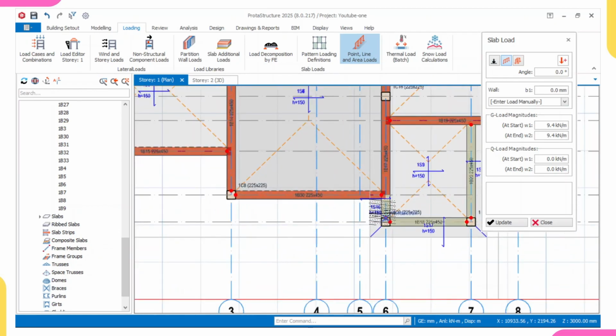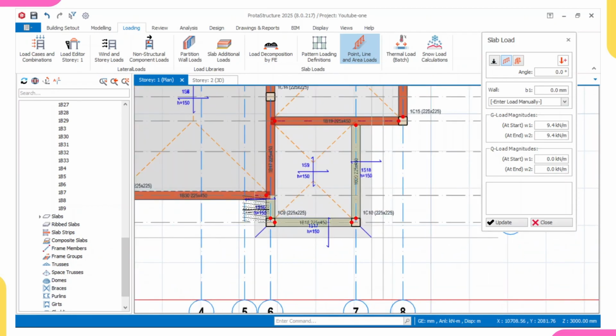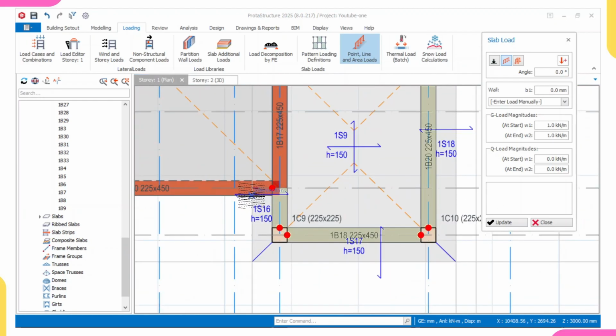But don't forget, this one now, here is no longer block wall. Here is a handrail. We'll be having a handrail here. So for handrail, I'll just like to use the unit weight of 1. I'll just like to use 1. This is not block wall.